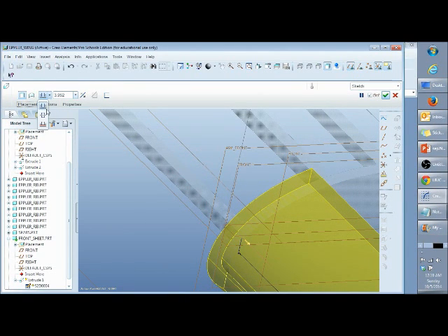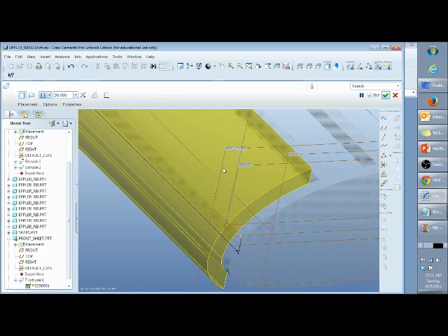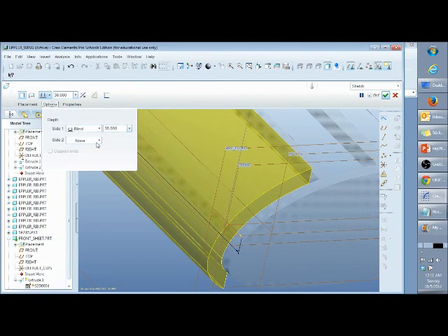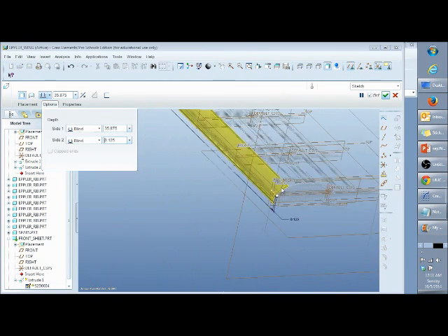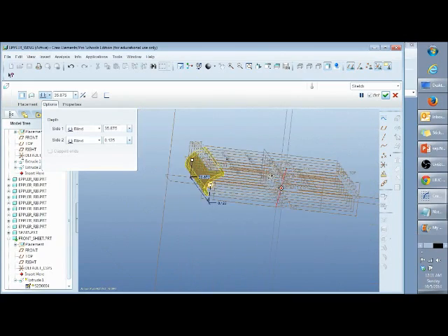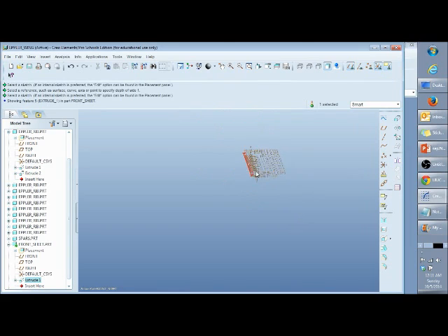This one's gonna probably freak out the same way. 36. What I'm gonna do is make that side of it options. This is a neat little tool because you can extrude out two different directions if you do it this way. I'm gonna make this one 36 minus 0.125. It's 1.125. Don't know if I pointed it out before in my other videos, but it will probably do math for you. Freaking awesome if you're too lazy to actually do it yourself.